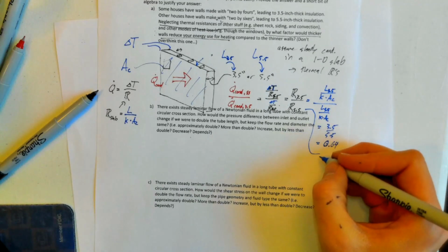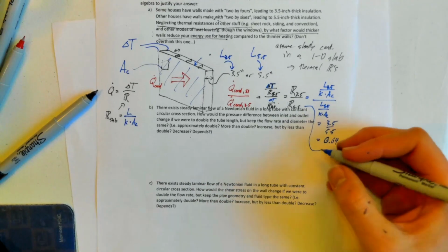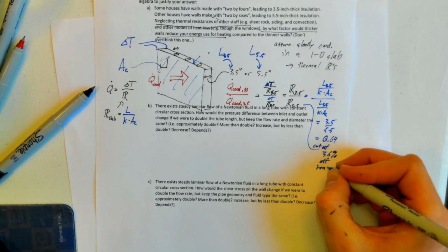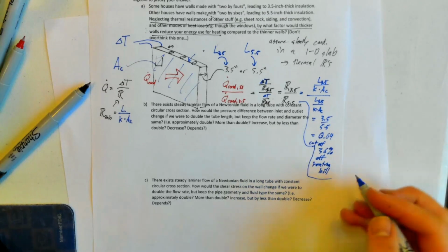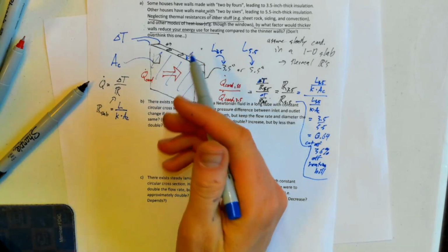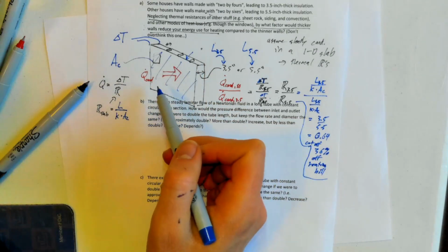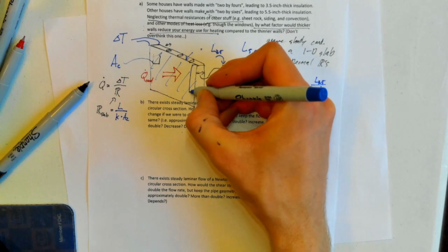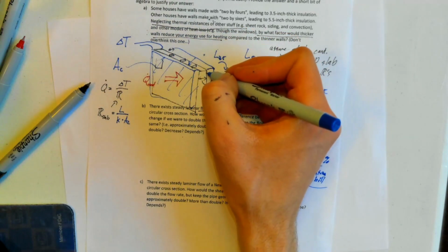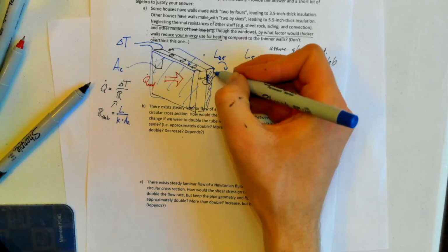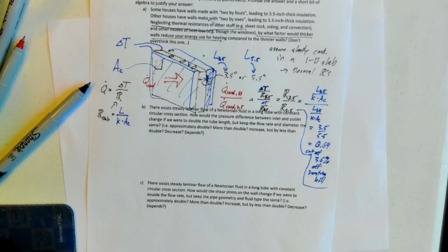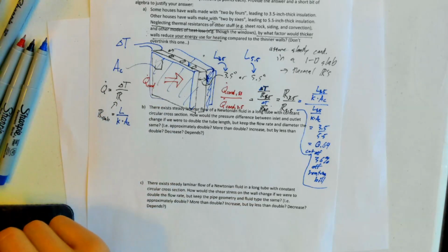0.64. So the factor of reduction, so basically I cut down 36% off my heating bill. So what's the moral of the story? Well, we can combat global warming by, for example, when we construct new houses, making them have thicker walls, or if we want to retrofit old houses, you can add a layer of insulation either to the insides, or if you're residing the exterior of your house, instead of just putting the siding where you found it, put down another layer of insulation and then put new siding on the outside. So if we make the walls of our houses a lot thicker, we can cut down on global emissions by burning less fuel to heat our homes.